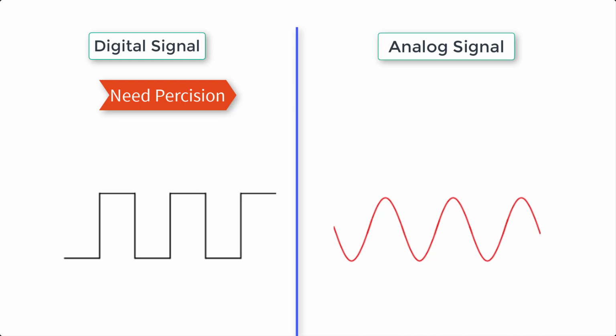If there's any varying in voltage from the source voltage on the board, there may be changes to the analog signal. There would also be changes to the digital signal, but with ranges, you would be able to still determine whether it was an on or an off state. So for example, in a digital signal, if my source voltage were to drop to 2.5 volts, I could not get to that 3.3 volts that would indicate an on state.